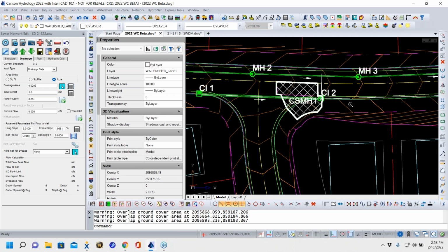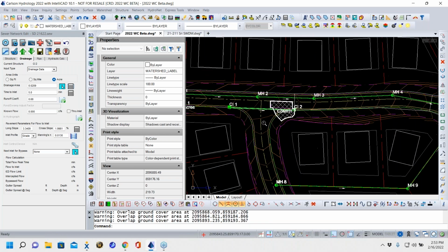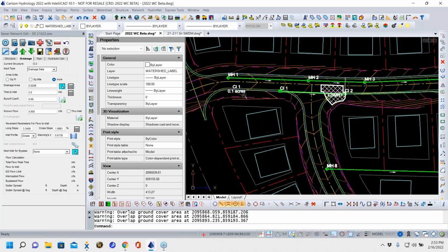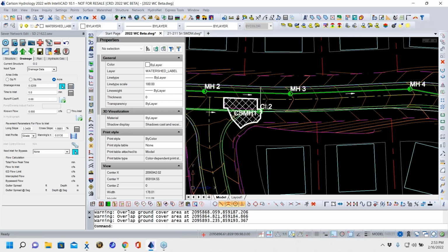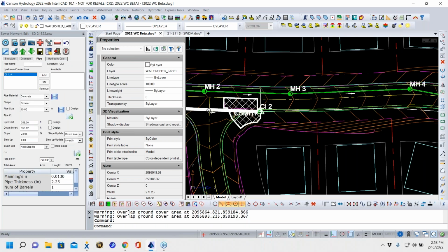He's really kind of a junction because this whole road falls off this way. So he's really just to get me across the intersection. And where I'm located, water's not allowed to go across the intersection, so I have to. You guys may not, but CI2 is in. Now, what did we get new? Oh, we got a pipe. And if you look, here I can specify that very first pipe size. And then all the rest of the pipe sizes will be 15-inch. The pipe material, let's go RCP3.